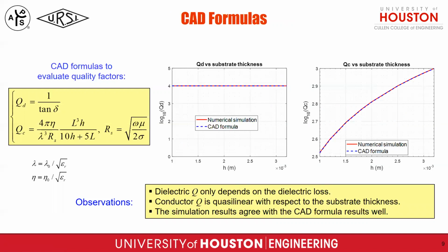For a cavity resonator, the quality factor is very important. Here, we propose some CAD formulas to evaluate the quality factor. In our simulation, we use lossy dielectric and lossy copper, so we need to consider the dielectric loss and also the conductor loss.